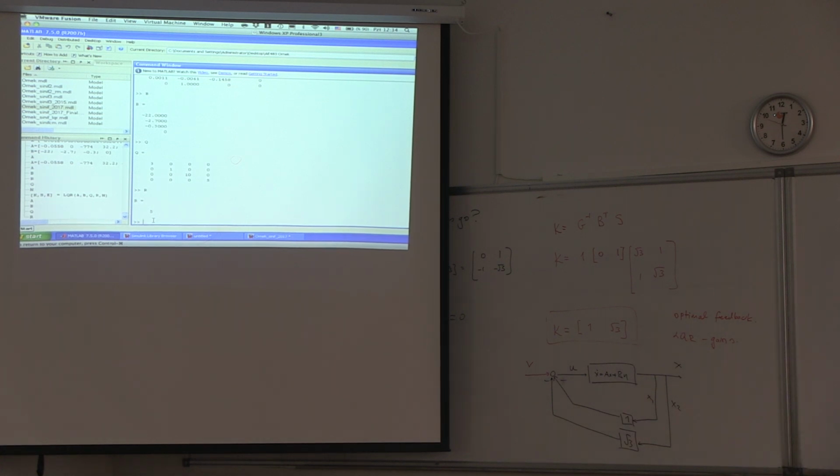Given this Q and R, I would choose this syntax, LQR equal to A, B, Q, R, and N. N is equal to 0 because I don't want that cross product. Remember? If I say LQR, A, B, Q, R, N, I should get the feedback gain K, the algebraic Riccati solution S, and the closed-loop eigenvalues. Boom, and that's your result.